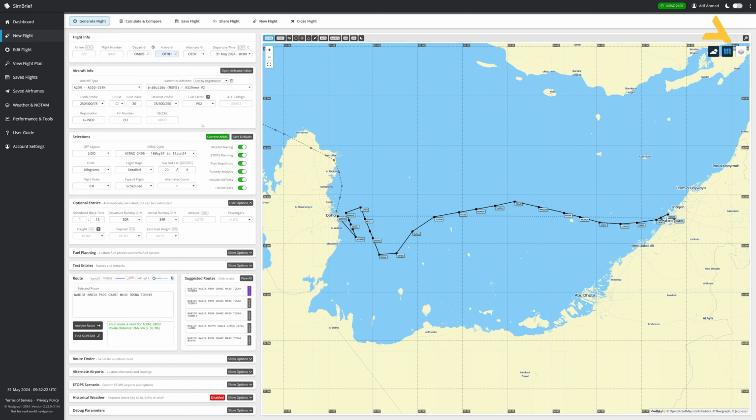But remember this thing, it's kind of a tricky thing. And with this plane, it works a lot, because if you're entering this number 30, then the speed on the autopilot is really less. So if you are, let's say, flying at or below 10,000 feet, the speed will remain at 250, provided there is no constraint during the departure. But after 10,000 feet, when the plane climbs to 35 or 38,000 feet, as you have selected a small number, the rate of climb will be less. So it will take a long time for the plane to actually reach the top of climb. So this is a bit tricky.